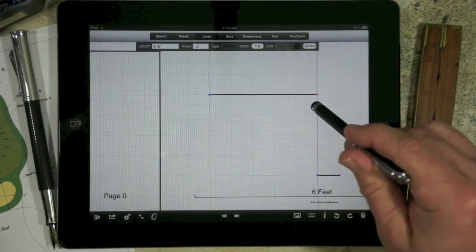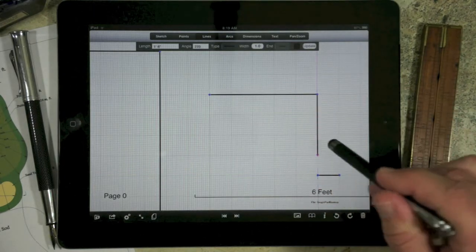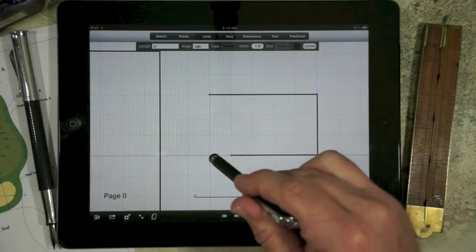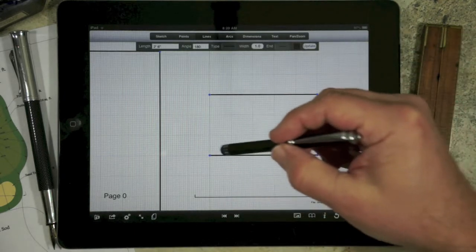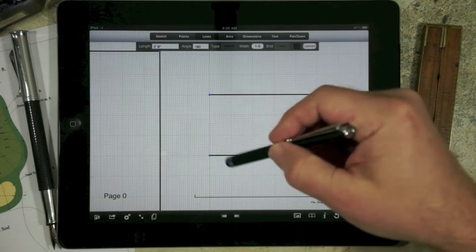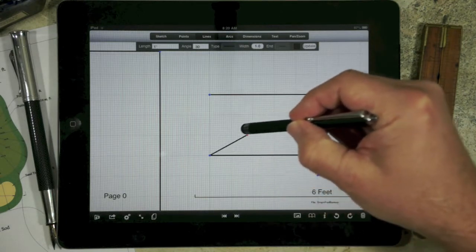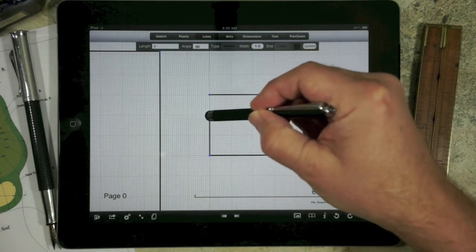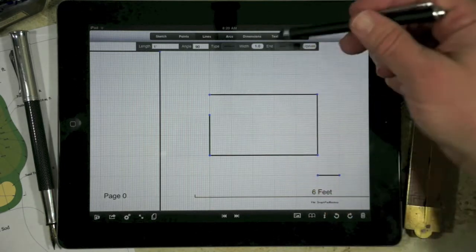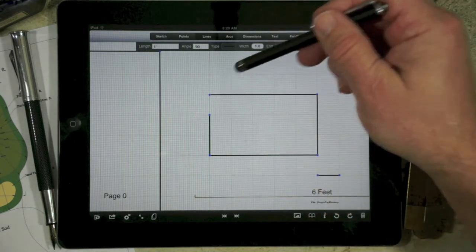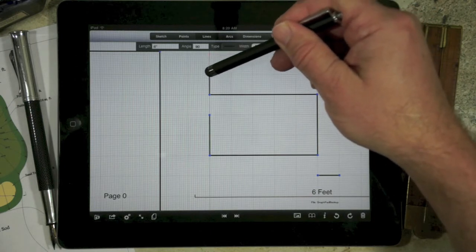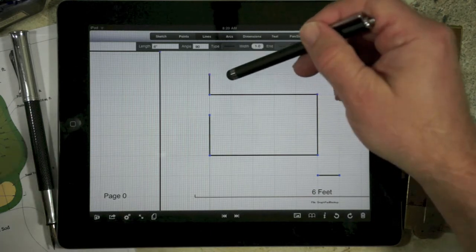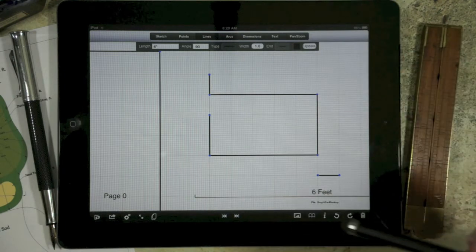So we'll notice as I draw that it's precisely on the grid, and that's because of this grid size. Halfway distance between the grid size, it's actually going to look around for the point, and you'll notice that I was able to grab that point even though I was nowhere near it. Similarly, and hopefully this will show up in the video, I'm way up here, but it actually says, okay, obviously I was trying to get that particular point.